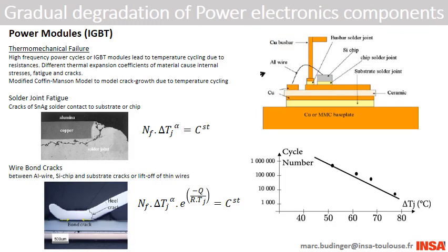In the power electronics domain, power modules, such as MOSFET or IGBT transistors, are composed of silicon, insulators, and electrical conductors with varying thermal dilatation coefficients. As a result, thermal cycling implies mechanical constraint variations and thermomechanical fatigue. Rupture can occur on the chip's braze joints or around bondings.